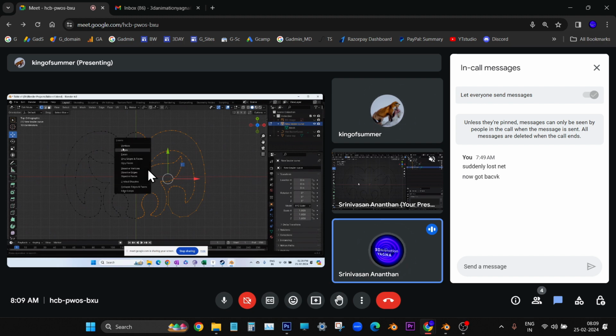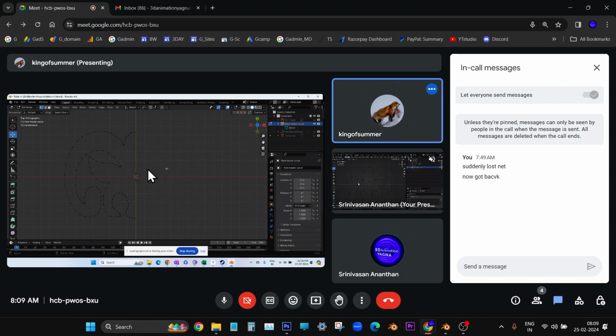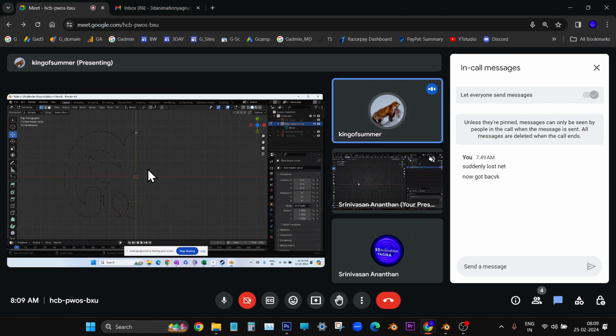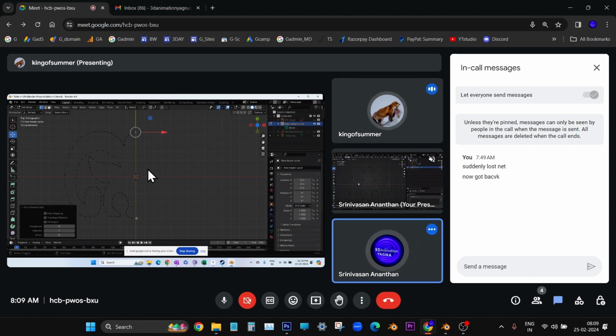Press delete. Yeah, vertices first. Yeah, nice. Now the two deselected vertices on the top and bottom, you select only those two vertices. No, no, Alt A. Only that vertex on top. Yeah, that one. Shift to select this vertex, the bottom vertex. Both of them should get aligned on the middle. If it's not, you just try it.